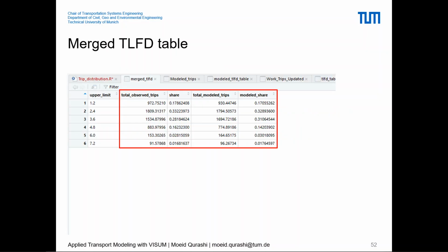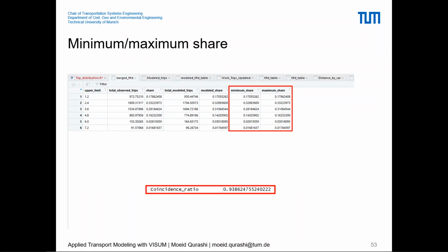Now, so that's it. So that's basically the idea of trip distribution, where we basically started from the productions and attractions that were the output of the trip generation, and then to convert these productions and attractions into an OD matrix, we needed to do the step of trip distribution, and this conversion requires a gravity model that defines which zones are more likely to go to which zones, right? So the productions from which zones would likely go in the direction of which zones. Yeah. So this is done by estimating a gravity model.